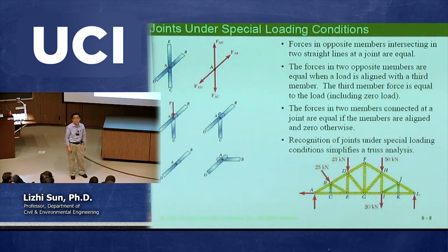So back to this joint J now. You can still say there are 4 members connected to joint J. I fully agree. But the conclusions we got, based on what is called the method of joints, are based on forces. The reason you have a force is of course related with the members: I cut a member, I give a force.